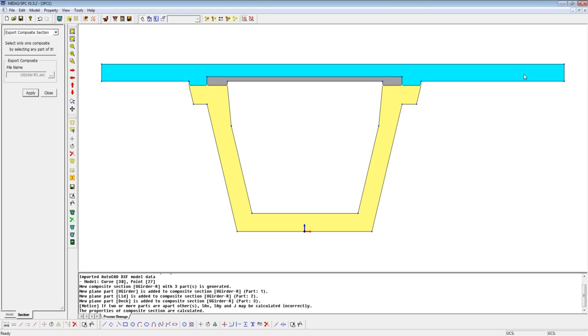So Abul, I would suggest you not to use rigid links. Instead, just use the dummy members, or let's not call them dummy members, I'll call them transverse elements, with the cross-sectional properties of the deck slab, or based on Hambly's equation, which is very useful if you are working on several cell box girders.